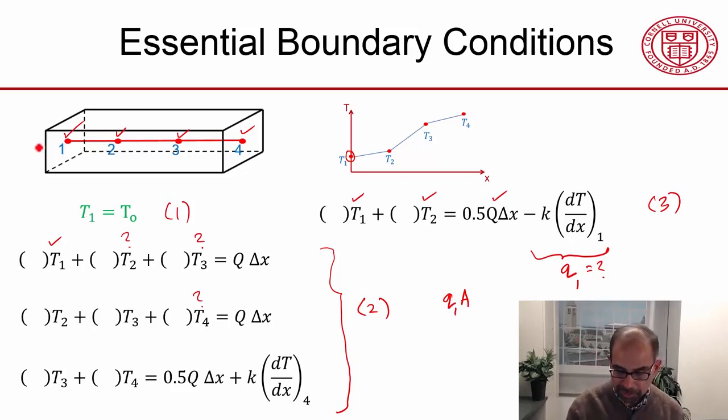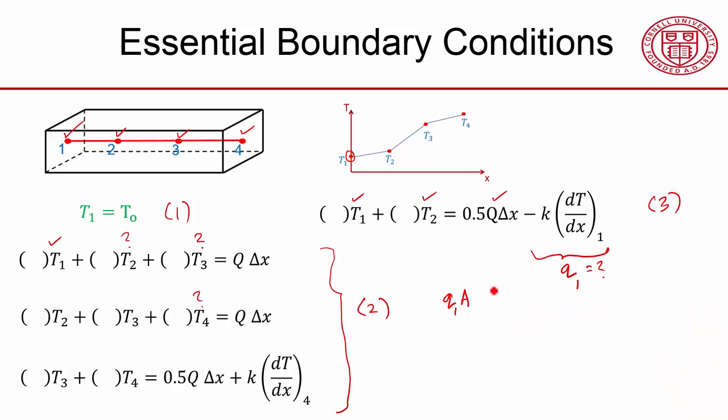So I can check that the heat flow coming in, that's this over here, plus the heat generated, which I know, that's Q times the volume, is equal to the heat going out, which I know from the boundary condition. So this entity turns out to be very important to check the energy balance, and it's called a reaction in ANSYS. And you can request what the reaction is from ANSYS and then do a check on the energy balance, and you'll be doing that.